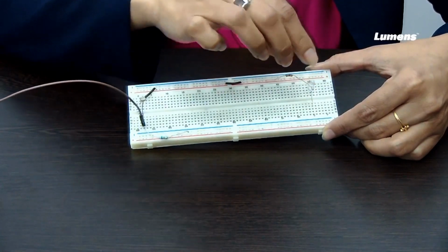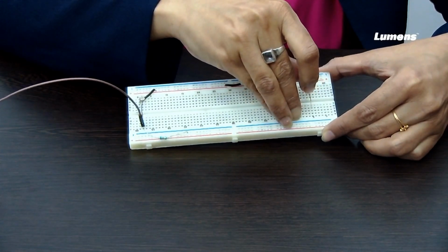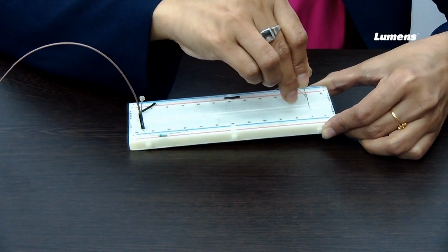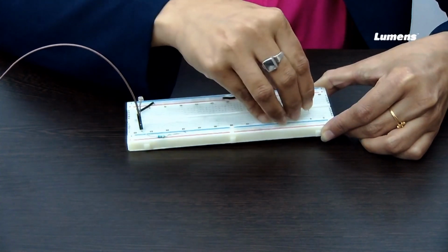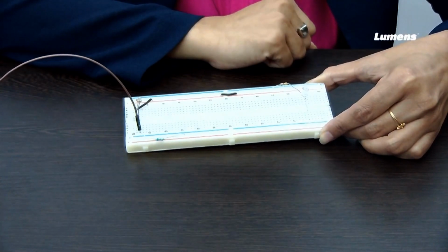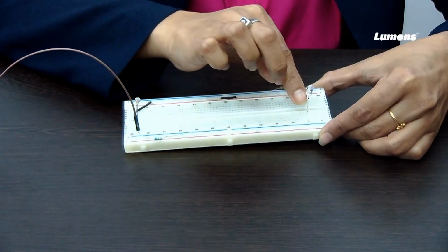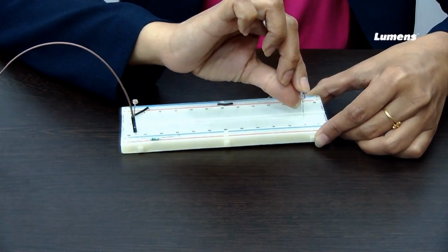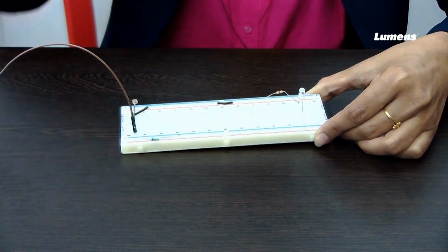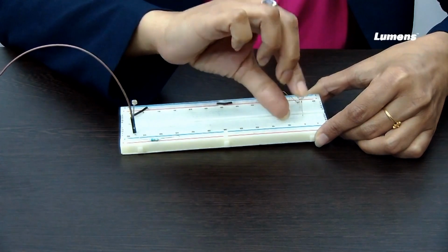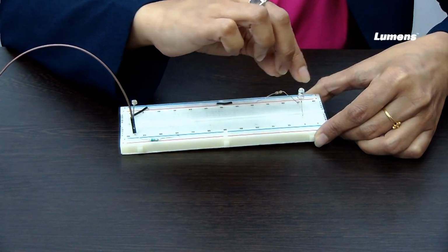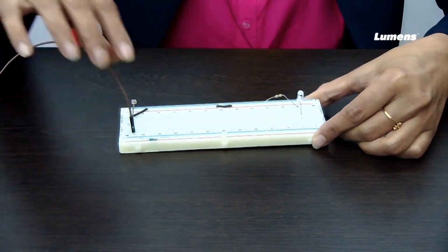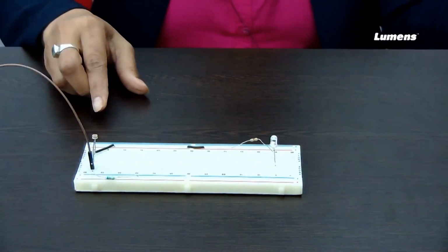And this LED is straightforward. For the LED, we are connecting the anode using this resistance to VCC. So, this is connected this way, and the cathode will be connected to the PWM port D3. Okay. The PWM port, as we already know, has already been discussed, what we are doing with PWM. So, we are connecting there because we need this LED to glow with different intensity. Okay. So, let me do the connection with the STM board first.